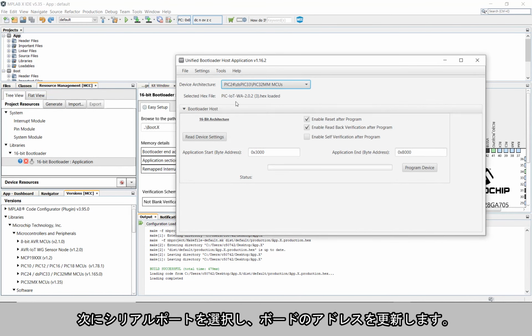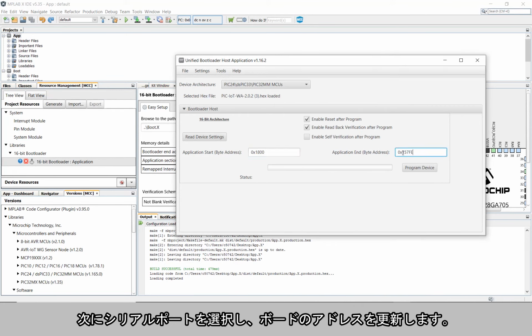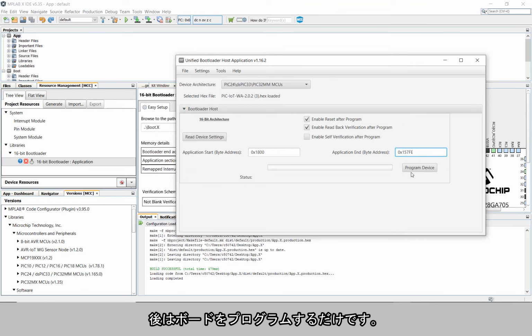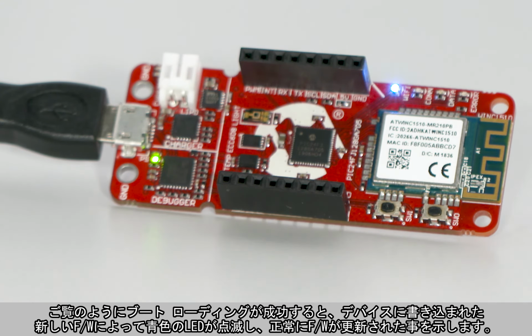Then select the serial port and update the address of the board. Now all you need to do is program the board. On successful boot loading, as you can observe, the new firmware on the device is now blinking the blue LED, indicating a successful firmware update.